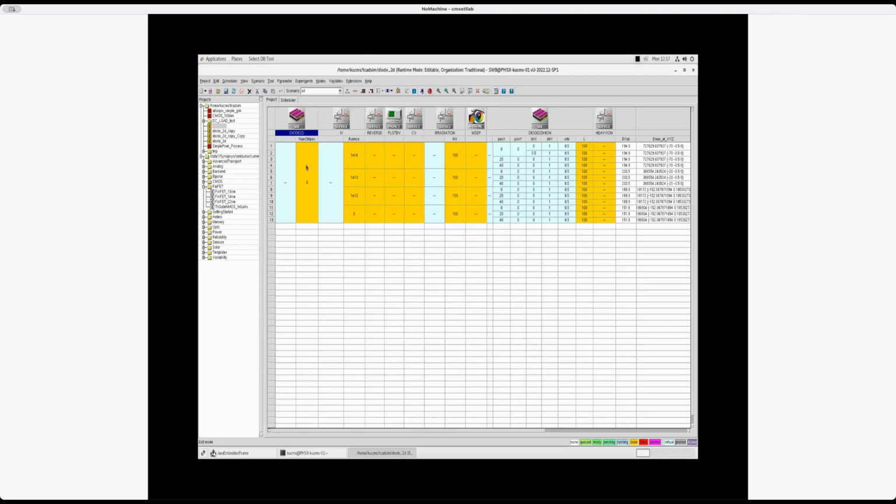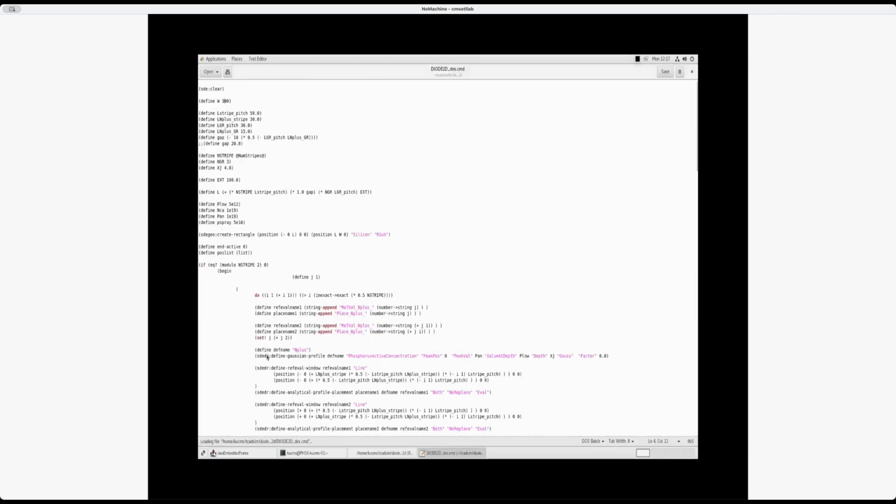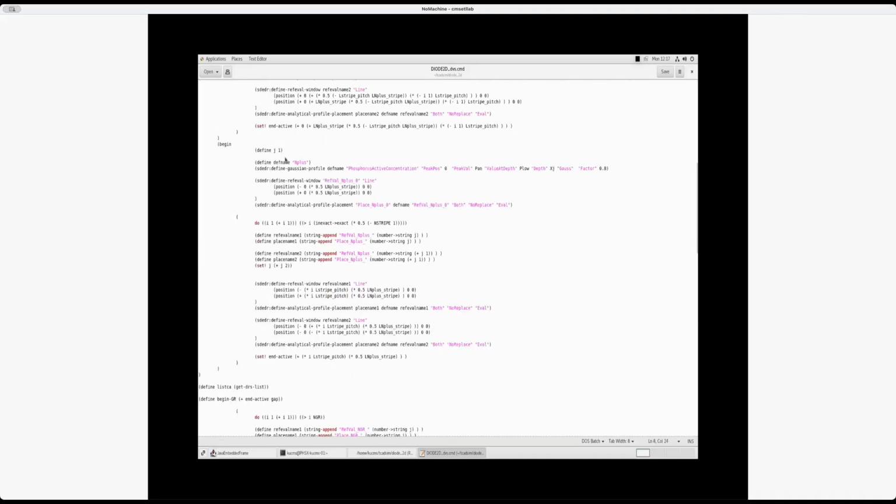Then you have, let's say if you right click here, you also can edit the templates that are going to be your input. So normally the one that's always needed is a command. If you go to edit input command and the file doesn't exist, it's going to create the file. Otherwise, it's going to open the script that we have defined already. It has the name of the tool and the suffix that's set in the tool parameterization that I was showing before. And here we have a simulation script.